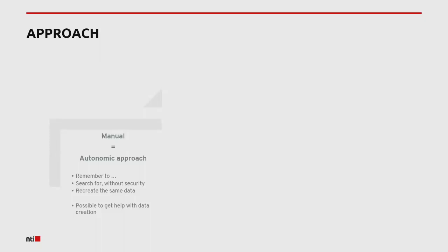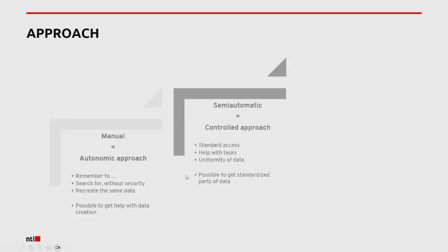So you can control the appearance of the PDF file, and you can control the naming and the file structure of the PDF files. The second step could be the semi-automatic, which we also call event-based. So every time you save an Inventor drawing, change a property, check into Vault, whatever event you could imagine, can basically trigger the publish of a PDF file. It could also be a lot of other things that are triggered, but just to give you an example.